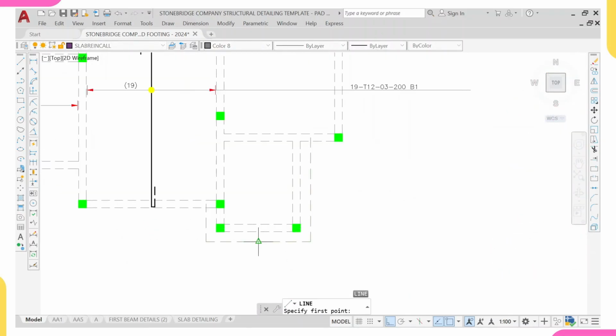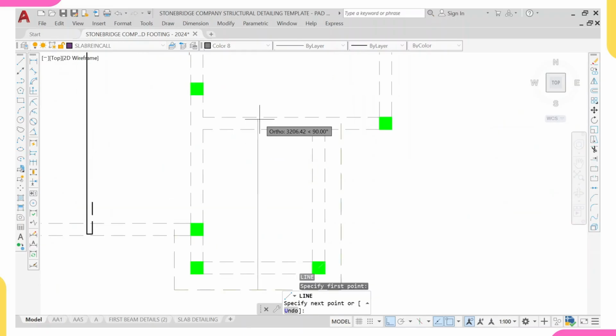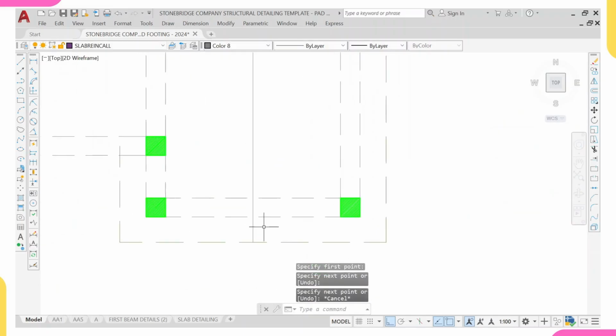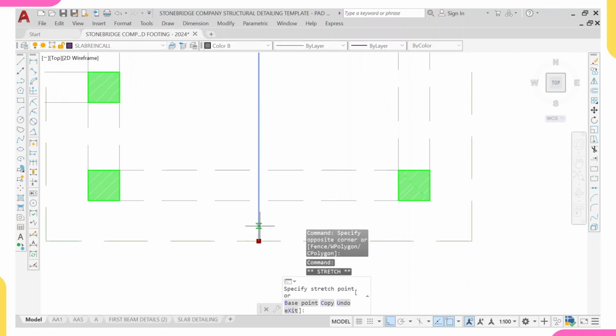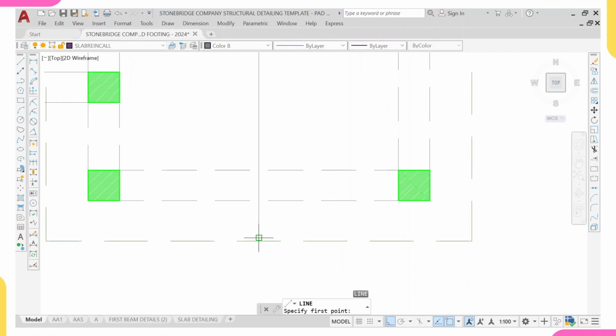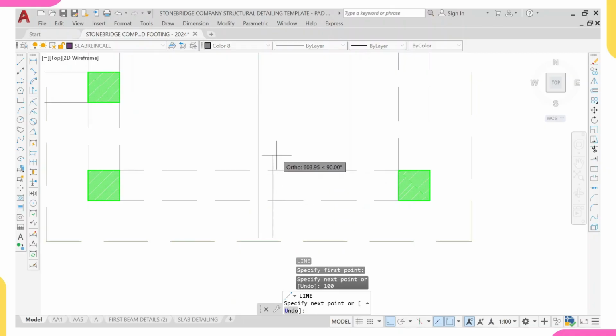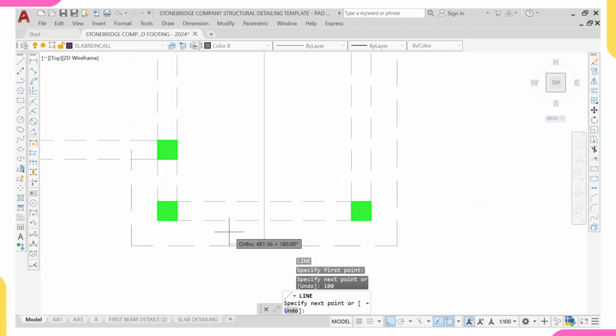I'll do L enter. So I'll be having this run from here and stop here. Then I'll come over to this point, click on this, and offset it by 20 by 25, enter, escape, L enter. So my sidebar is 100. We have explained how we got it. Then my lap, remember this is a cantilever. Yes, you can see it is a cantilever.